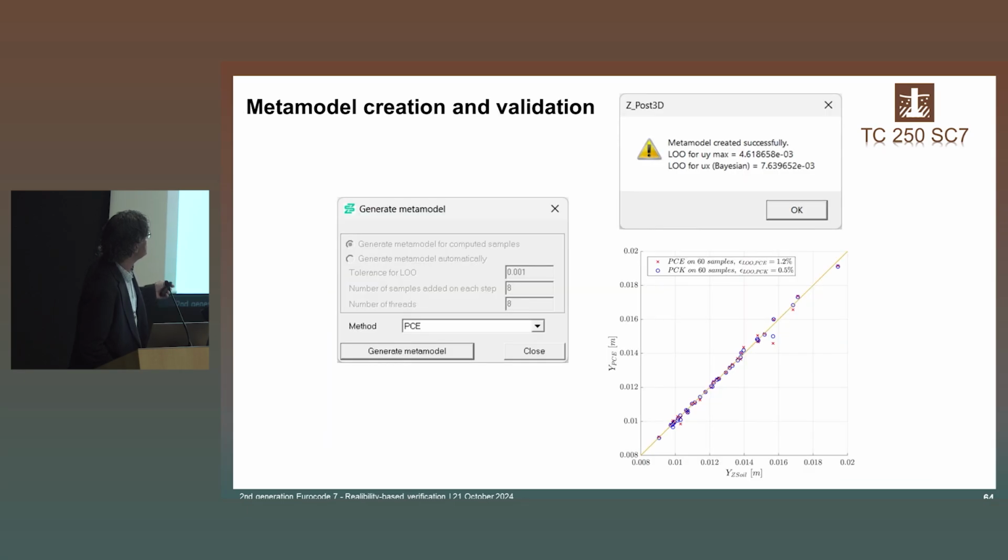and then using this meta model, I can compute a kind of continuous approximation of the discrete 100 computations. And this continuous approximation is just an equation relating the input variables with the output results. And you can see that there is a measurement of the quality of this meta model. So if 100 samples is not enough, maybe I have to run 50 more. But for the type of problems that we solve regularly, between 100 and 200 samples is enough to get a good meta model.